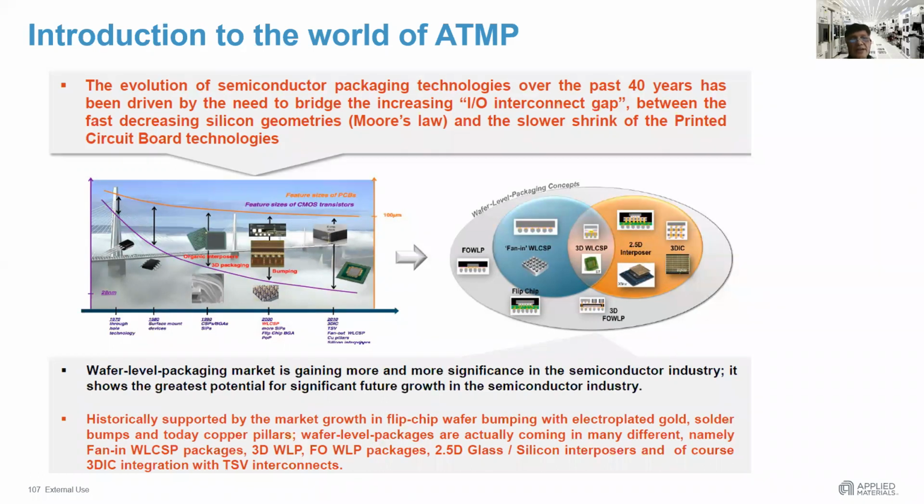And this is also creating an evolution from that original single die assembly, test, mechanical marking and packaging to wafer level packaging. And wafer level packaging is critical because really you are now processing everything on a wafer, and we will see a little more of how this happens a little down the line.